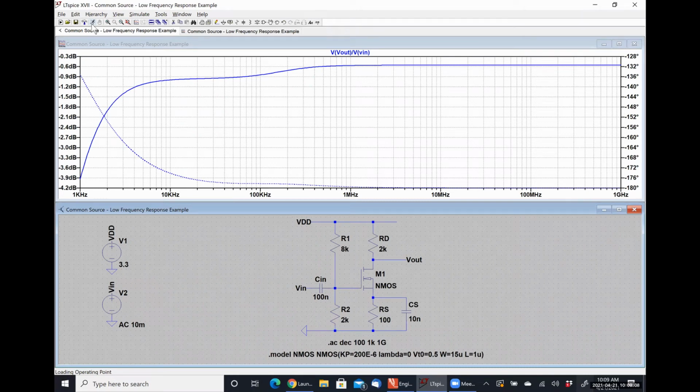Nathan, what's up? So the poles are where it sharply turns. Right. And the zero is the frequency where it goes flat. So everywhere we see a pole, we should see a slope of negative 20 decibels per decade. Everywhere we see a zero, we should see a slope of positive 20 decibels per decade. So here, where it's turning down, this is negative 20 decibels per decade. Then when we see that zero, we add positive 20 decibels per decade to that slope, making it completely flatten out until we see that other pole where it rolls off.